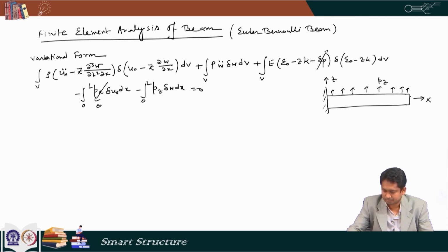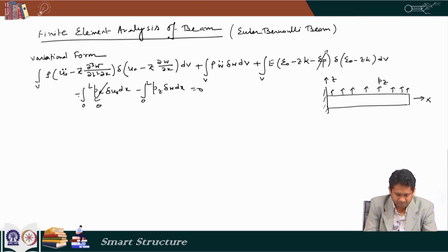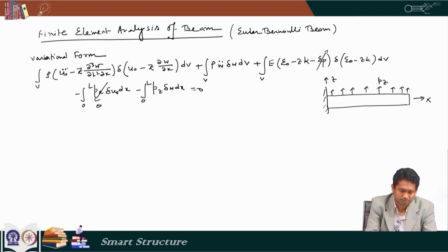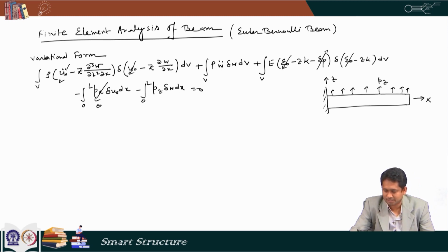and this as we do not have any asymmetry with respect to the neutral axis. So, we do not have any coupling between the in plane and the out of plane terms. So, under a pure transverse load, I mean the load which is applied along the z direction, this beam will deflect only in the z direction. So, there will not be any u0 component induced. So, we do not have these as well, and we do not have epsilon 0, the mid plane strain as well.